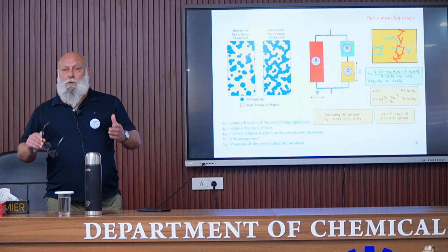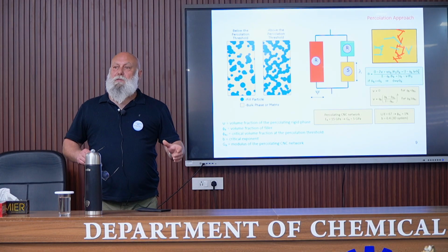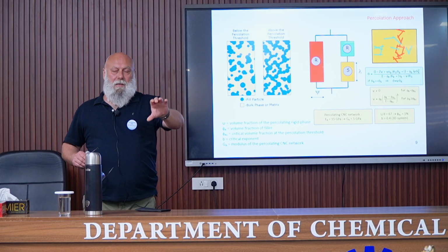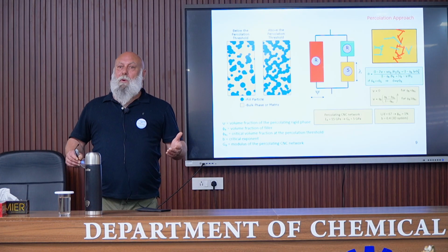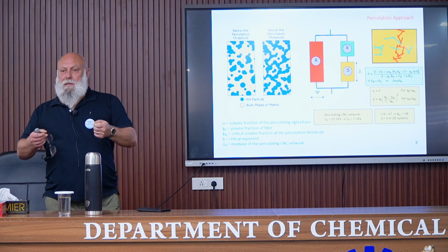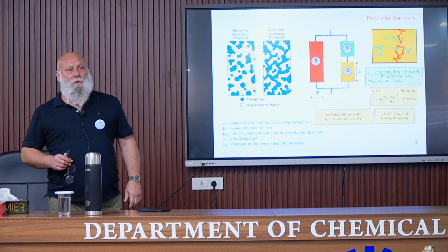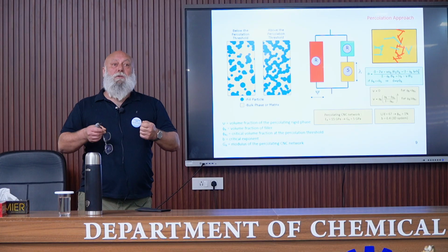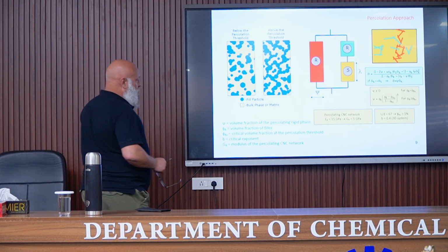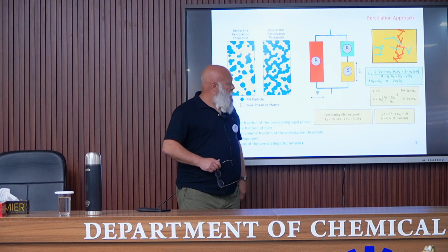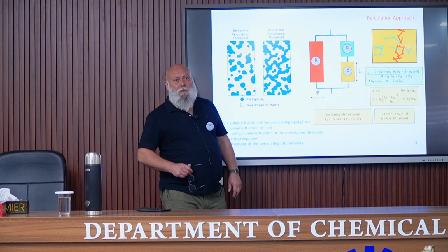For this, you just have to use an aqueous dispersion of nanocrystals. It can be cast and evaporated. We obtain a nanopaper, and a tensile test can be performed on this nanopaper to determine the stiffness of the network. And so it was done, and a modulus of 15 gigapascal was obtained.